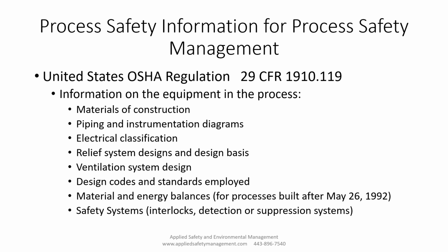And then when it does go somewhere, how are we controlling this? Are we looking for a relief system? Do we want to have some pressure in there, or do we just want to have an open top, and the open top goes to a scrubber and we're looking at ventilating the process? So there's a lot of different things to really sit down and consider. We're going to look at the design codes and the standards out there.